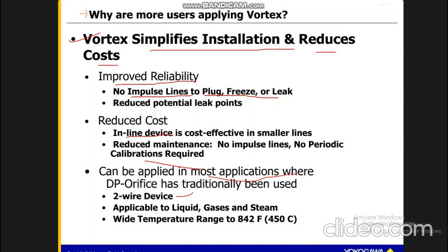It is a two-wire device, applicable to gas, liquid, and steam, where the temperature range is, you can see, 450 centigrade. The first thing is that it is very cost efficient, and the reduced cost is due to no impulse lines or periodic calibrations being required, and that's all.